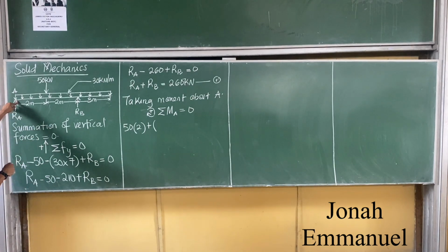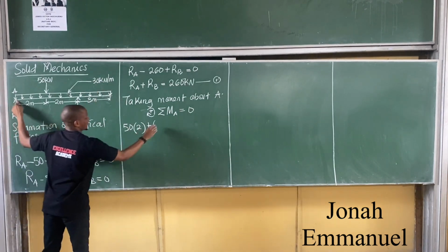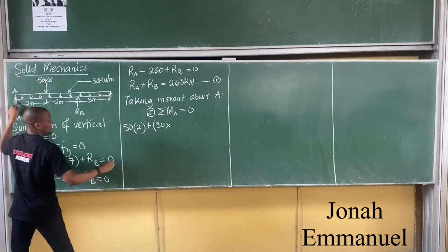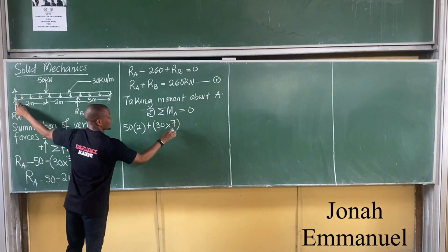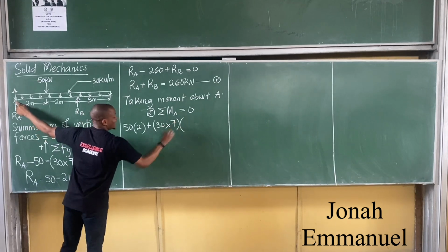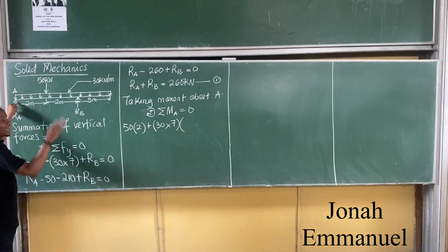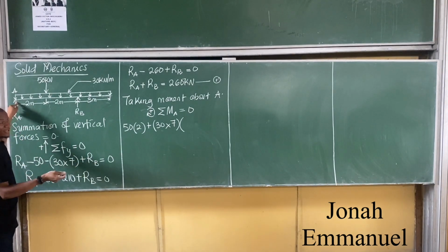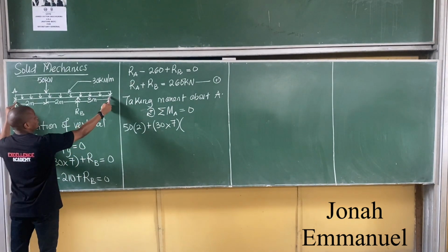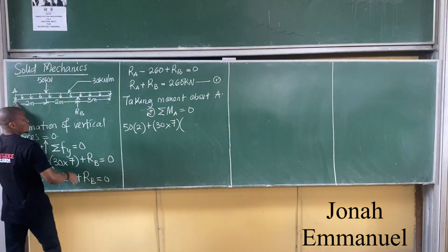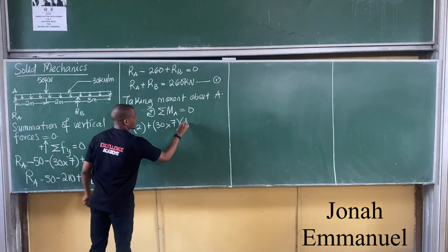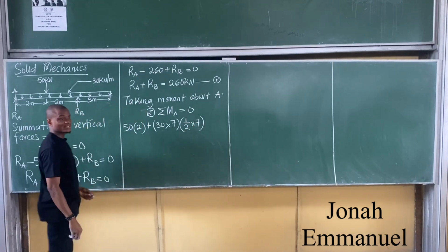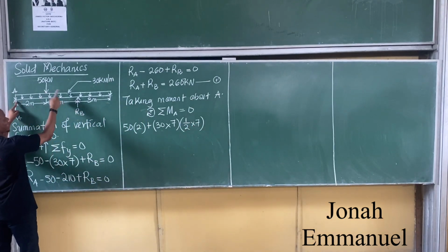A point load. How do you do that? Multiply the UDL by the UDL distance, 7. This is now the force. Next up, get the distance. We said it acts at half of the UDL distance. That was the hypothesis there. My distance here is 7, so it will act at half of this, half of 7. So I work with this force and this distance.